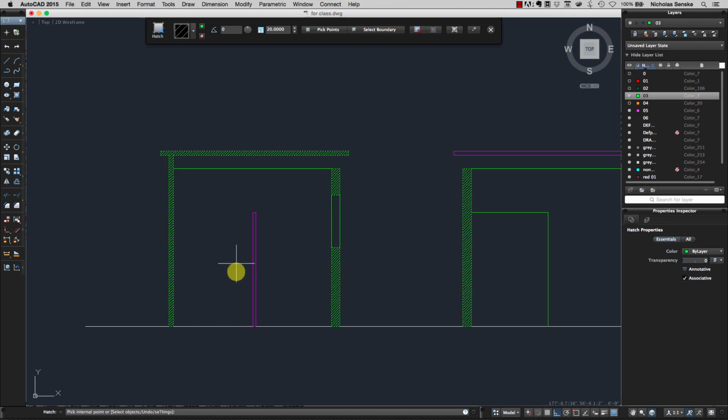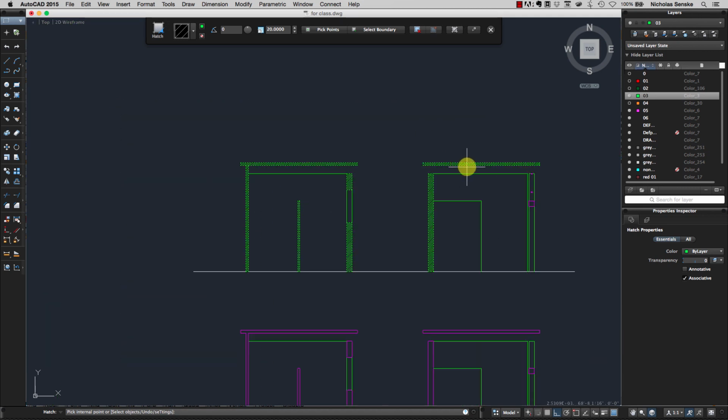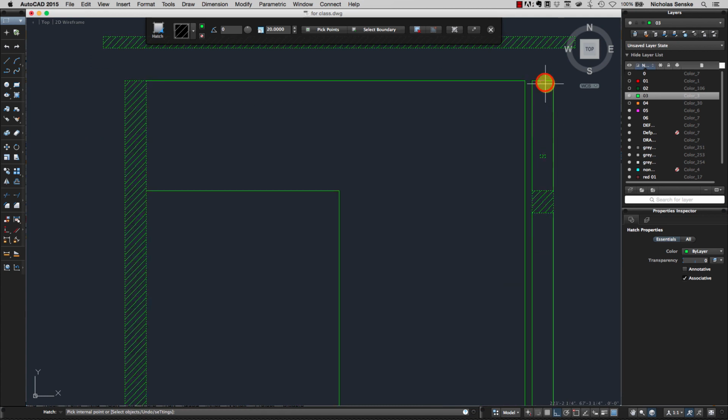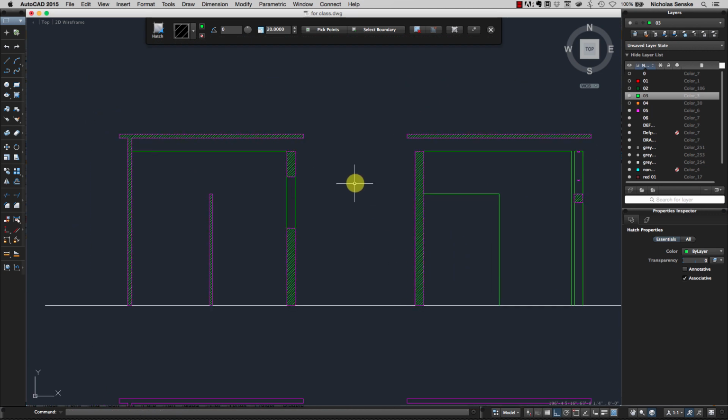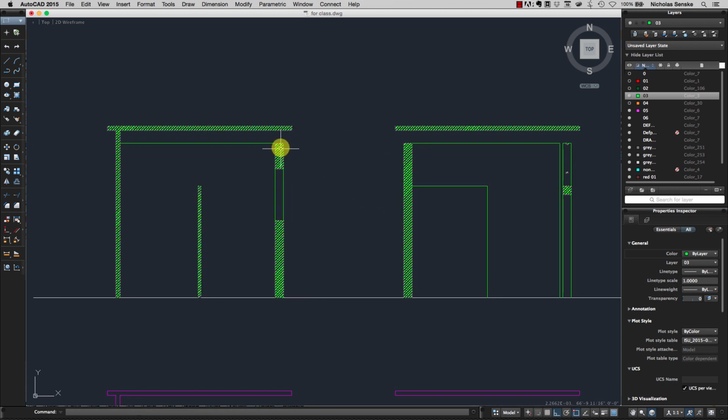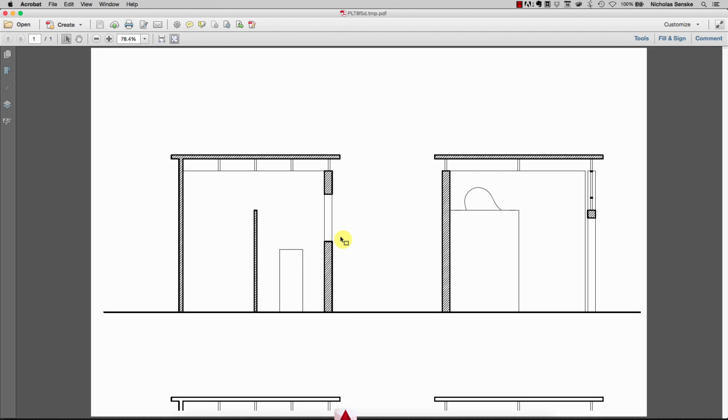I'm filling it in green because of the line weights. There are so many lines that it's going to look like a solid fill, but if I used a darker or thicker line like a 5, it's going to overwhelm. So it still has the border, but now these lines are this. If we go to plot, let's turn on these other things here. Yep, that's all good. That's pretty good, but it's not as dark and dominating as that solid fill. I am a big fan of the solid fill poche, but sometimes you want this kind of tone that's a little bit lighter, and that looks pretty good.